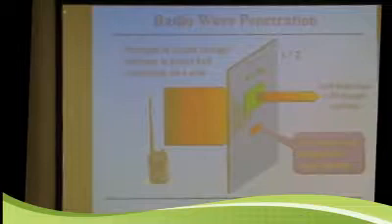Again, even a building. Some radio waves can make it through despite this, but this is one thing that if you're trying to make your communications within a building work as well as possible, then you'd like to have UHF because you're more likely to get better propagation through these openings that are at least a half wavelength on the side. Yes? Does the polarization of the wave affect which orientation the opening do?